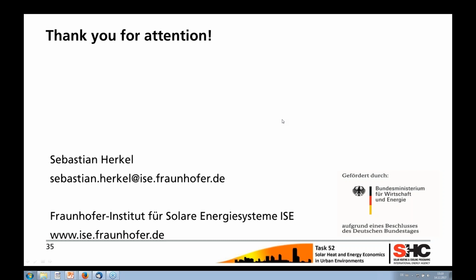About the cost competition, PV alone is not a heating system. You can use it if you use it directly, but then regarding CO2 impact, it's quite a disputable way. But if you combine a PV system with a heat pump, then you are, I think, more or less in the same range of cost. The issue is what do you compare? Because a heat pump is a mixed system.